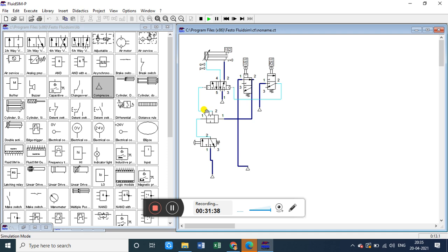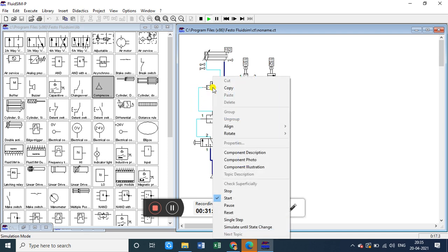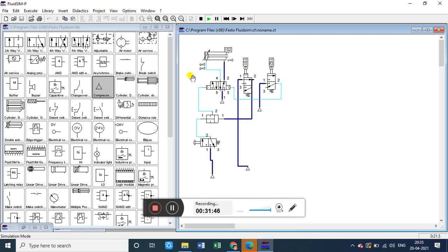I just dragged it like this. So this is what air operated. I have changed the properties just like we change by making right click. Now it is in run mode, so you cannot change the properties. So this is 1s2 position, this is 1s1 position. You can see the 1s2 position for the piston. Now this is the 1s1 position for the rod end, and this is the 1s2 position for the rod end. Now you can understand how these are getting pressed and unpressed, same way pressed and unpressed. Okay, you will understand this.